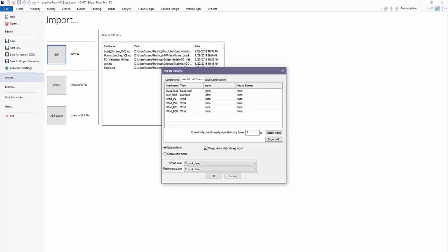This is a live load. I'm going to import the applied forces. Okay, those are basically zero. Those are just the dummy loads I created in my source model. And I want to map these to dead and live. Wind loads are identical. They're already called wind underscore P and P90 inside of our existing model, so we don't need to do anything with those.